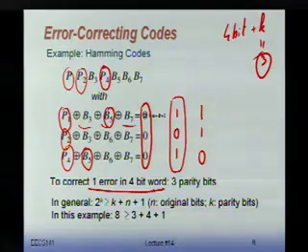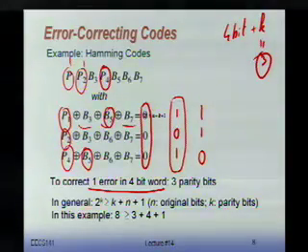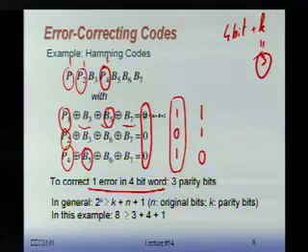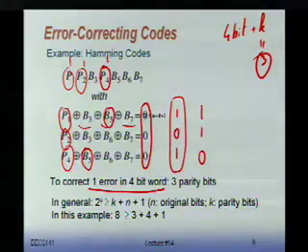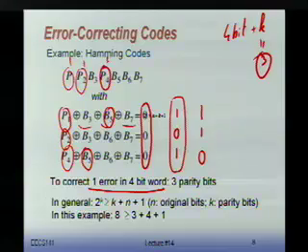Yes? So are the parity bits stored in the SRAM? Yes. So if you think about it, every 64 bits of a word, we're going to add k bits. And you can see the parity bits are not separated. They're not at the back of the word or at the beginning of the word. Actually, they're intermingled. And they are at positions 1, every power of 2, basically: 2 to the 0, 2 to the 1, 2 to the second, 2 to the third, 2 to the fourth, and so on and so forth.